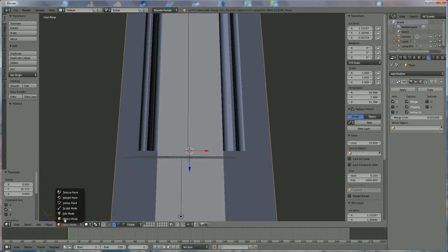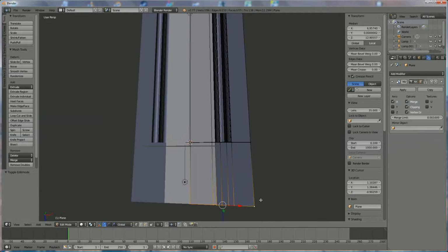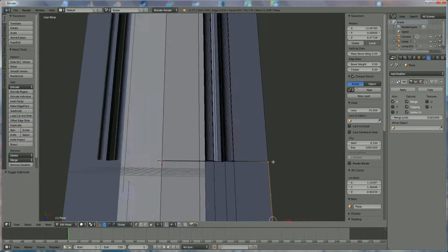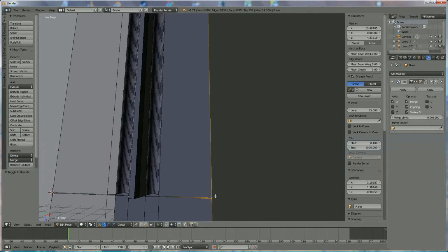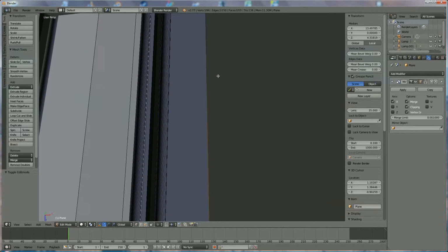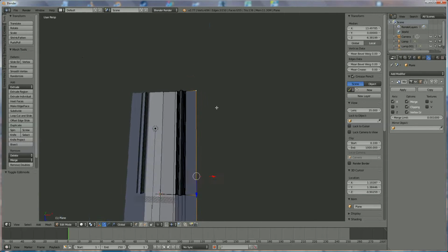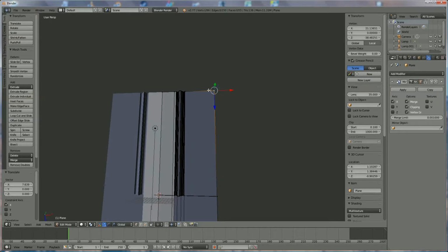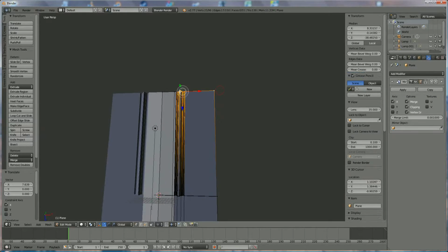Right click on that one, go to edit mode, select that point, shift that point, because we have 2 points over here. If you're not sure that you selected everything, you can choose the edge selection tool. Okay, I'm going to make that one larger, like this. Okay, and now I'm going to select that. To do that, I'm going to use the C command. Just press C and hold down the button, and I've selected everything.